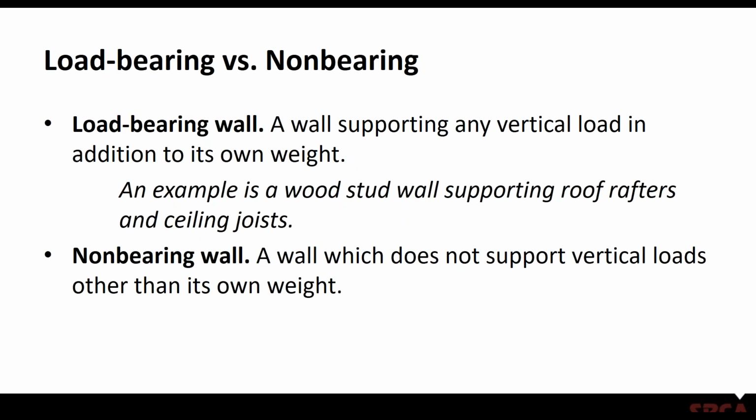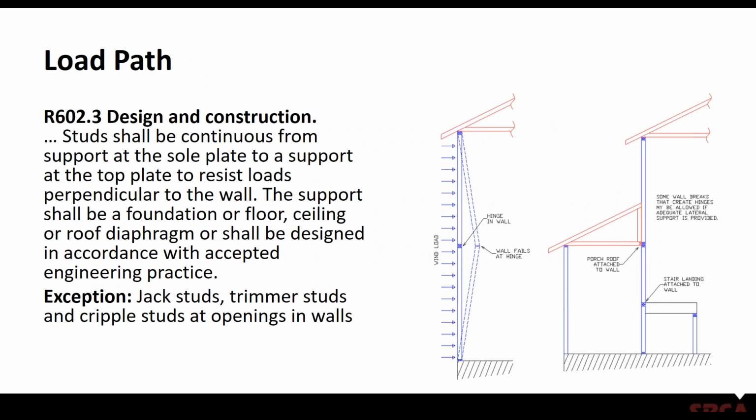One interesting note, a load-bearing wall is identified in the IRC as a wall supporting any vertical load in addition to its own weight. And then a non-bearing wall is a wall that only supports its own weight. A couple other items that can come up with load path.